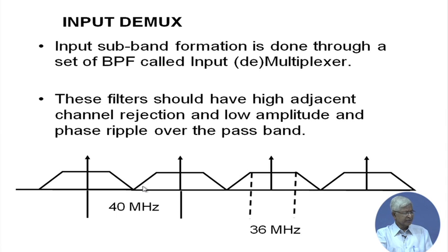Since the filter characteristics gradually increase, then stay steady, and then decrease, the steady part is taken roughly as 36 megahertz, the constant amplitude. So the transponders are each roughly 36 megahertz wide. Generally that is accepted by industry; I should not say standardization.